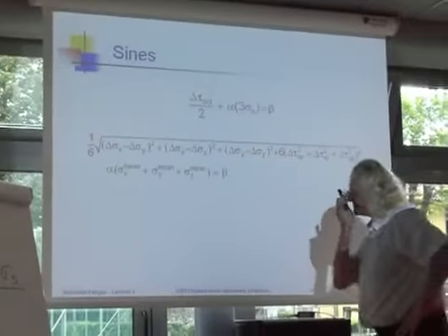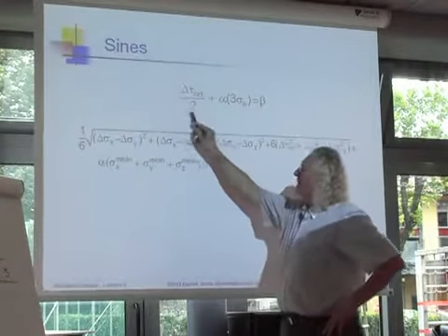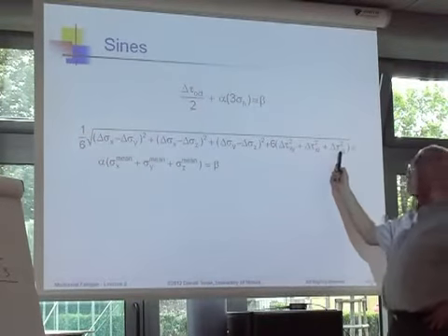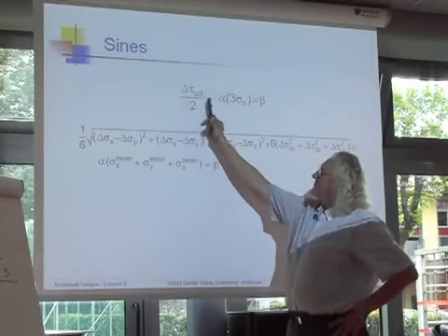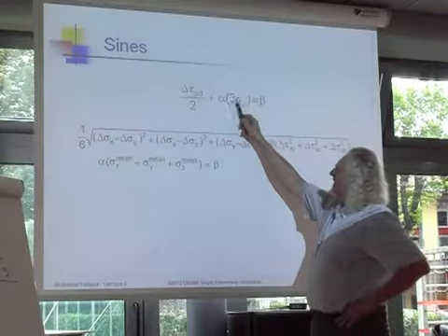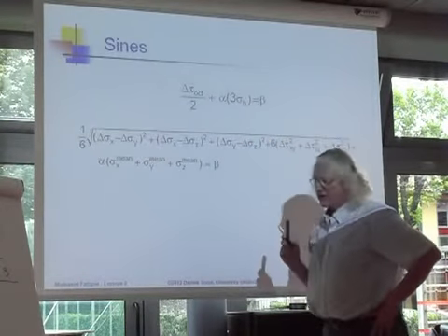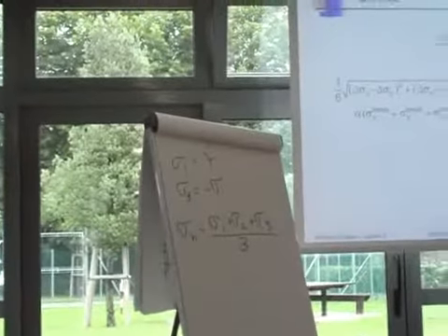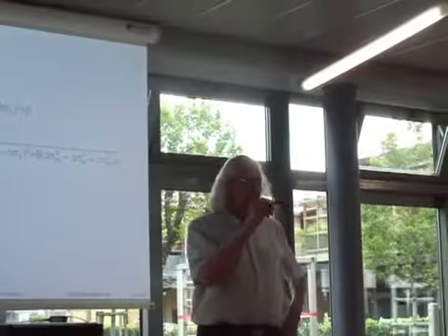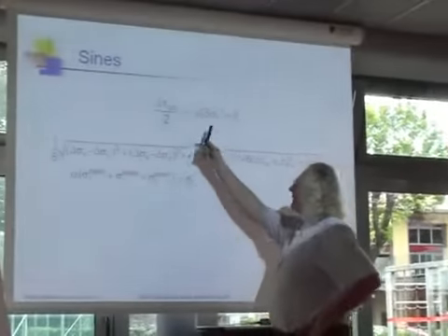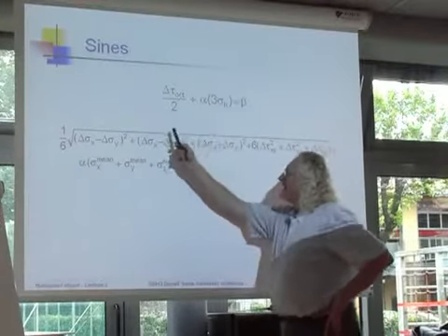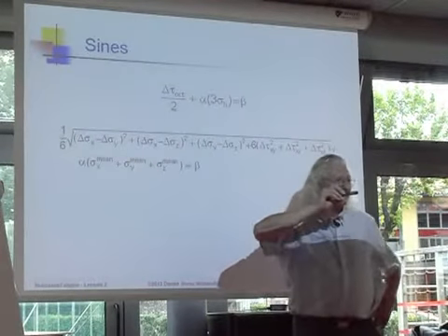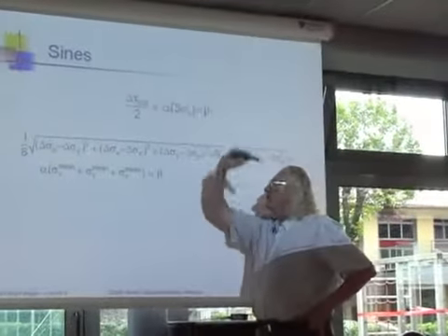Sines said, take the octahedral shear stress, which is easy to calculate because you can calculate this from the individual components of the stress. And now we're going to make a modification to the octahedral shear stress, and we're going to use the hydrostatic stress, sigma 1 plus sigma 2 plus sigma 3. This 3 balances that one. And then, well, you know, every fatigue theory needs an adjustable constant. And so you have an adjustable constant here, alpha, kind of a scaling constant. Sure, because I can test different materials, and some have more sensitivity to mean stress than others. And so, okay, there's my scaling constant.